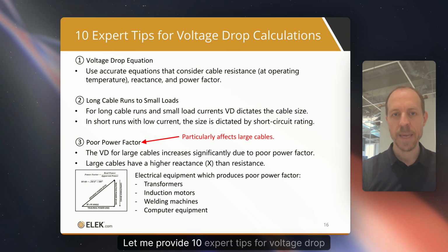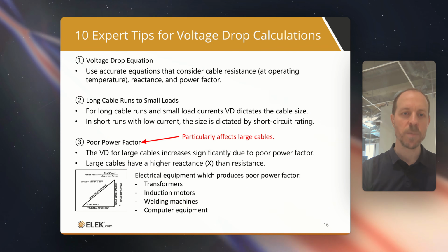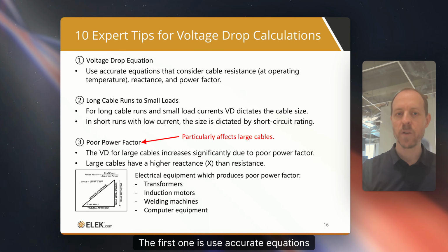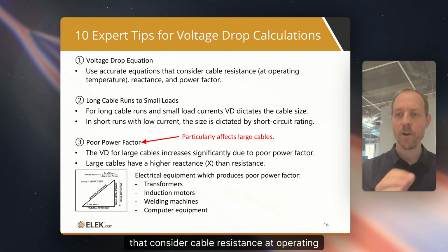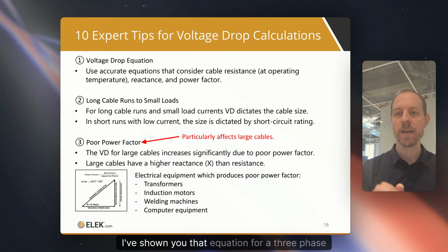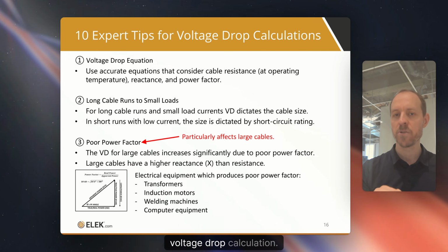Let me provide 10 expert tips for voltage drop calculations. The first one is use accurate equations that consider cable resistance at operating temperature, reactance, and power factor. I've shown you that equation for a 3-phase voltage drop calculation.